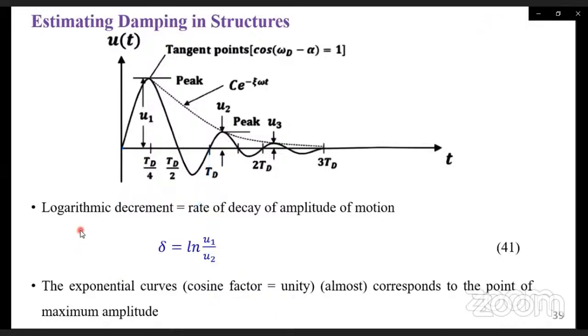So we have defined another terminology here, logarithmic decrement. And I believe we have defined enough because already we know our response. Response is how the motion, how the deformation is occurring in time. We can define the period of that motion. We can define and express the damped frequency. So our motion is complete. At any one time, using our expression and the curve we developed, we can know what is the amplitude or what is the displacement, and at what time maybe the motion will come to a stop.